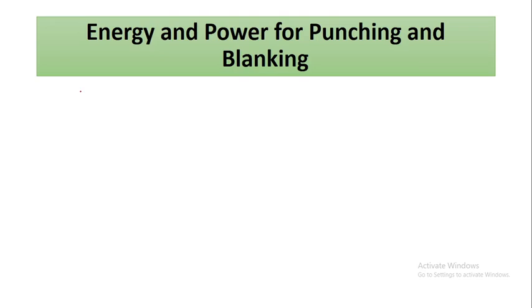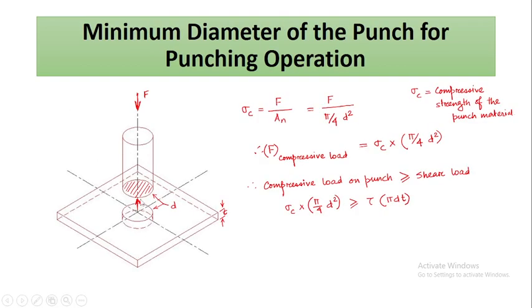So we can say in this case that while we are applying the punching force, what is the amount of punch travel that is taking place? Basically that is the energy required for the punching or the blanking operation.